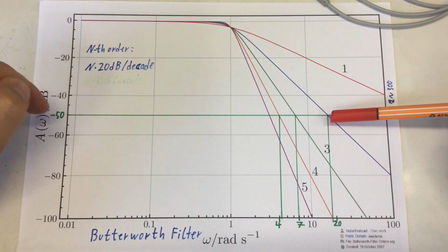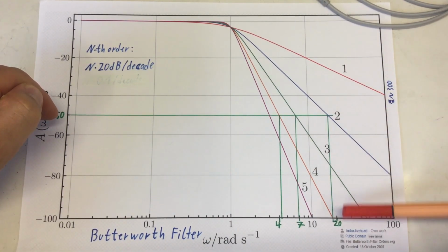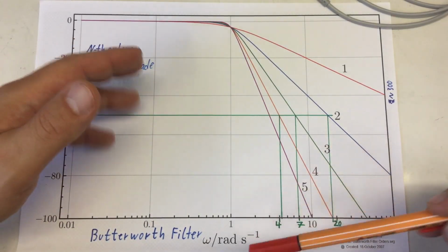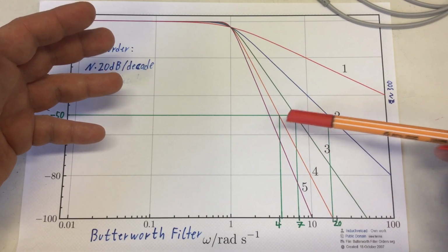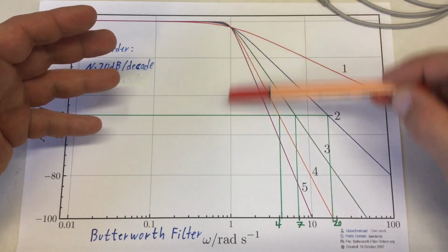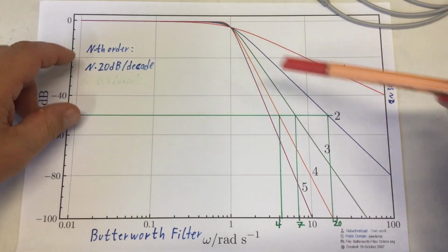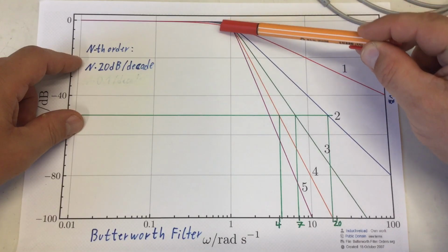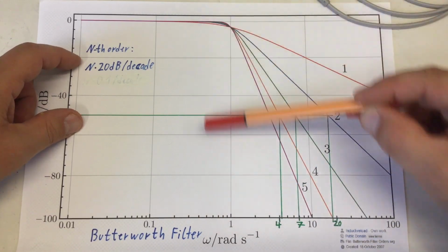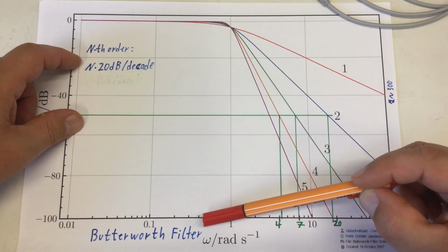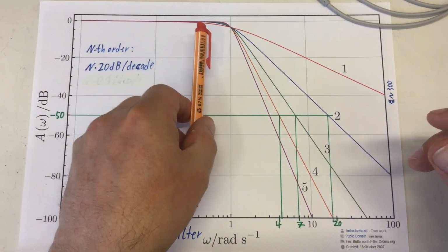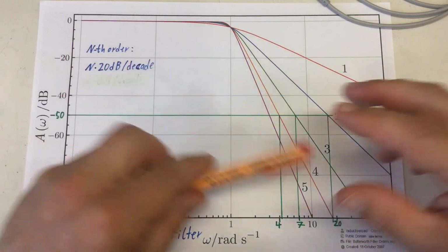It joins our minus 50 dB attenuation line at about 20 of the frequency scale, meaning PWM frequency of 980 divided by 20 is about-ish 50 Hz here for the cutoff frequency. It also deviates from the 0 dB line a lot later at about 0.5. So 50 Hz times 0.5 makes 25 Hz bandwidth for our analog signal.